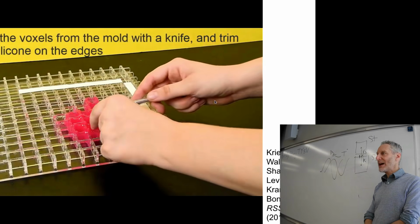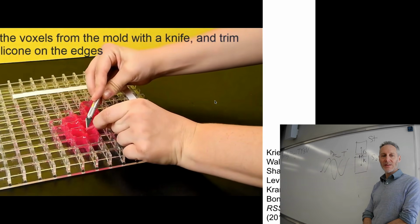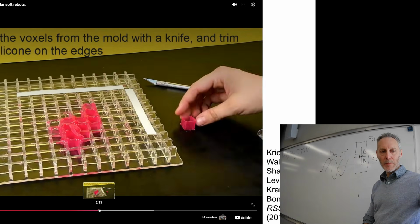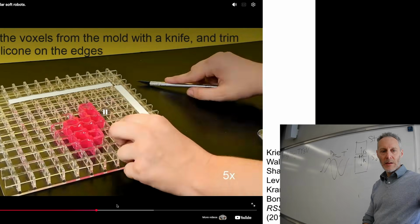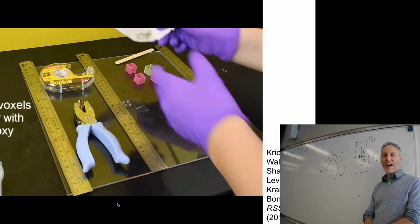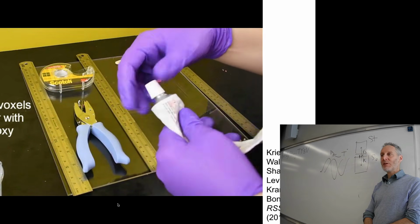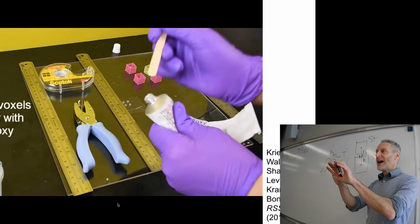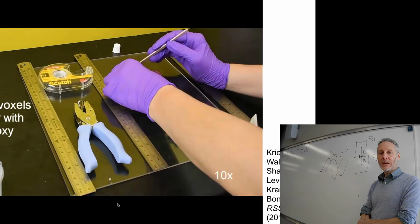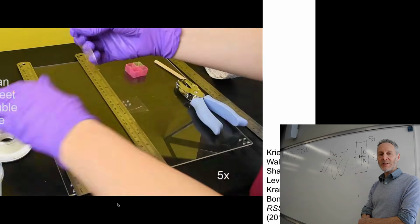Okay, so now the dragon skin has set and it's become solid rubber, solid silicone. We're going to gradually cut it out. And now we've got our soft hollow cubes with 5 of the 6 faces. Remember that I mentioned when we built the robot, some of the neighboring cubes had a little air passageway between them. So here's my then grad student Sam gluing 4 of these pieces together.